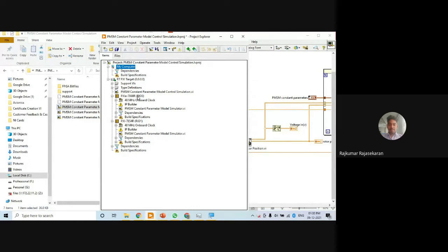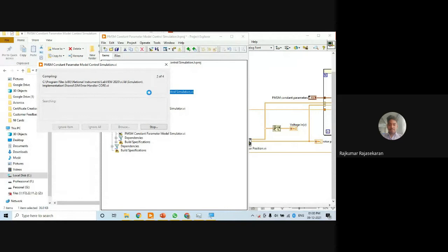So ideally, if you see, this is a controller which will be running under a PXI hardware. PXI hardware will be RT. RT means real-time controller. And you might be wondering how to program a real-time hardware. Of course, as I told, LabVIEW is used to program FPGA, and LabVIEW also has support for programming real-time hardware. We don't need to learn embedded C as we used to previously. The same graphical system, like we use for simple programming such as addition, could be implemented to program an RT computer as well, a real-time computer.